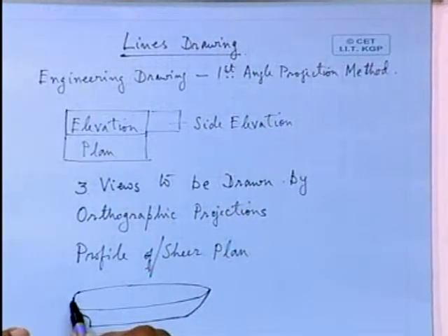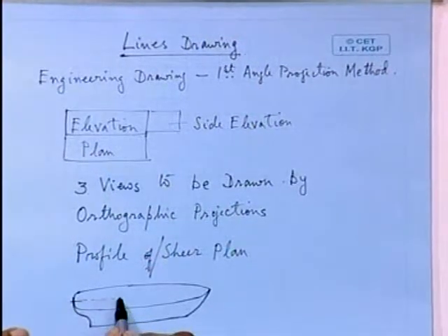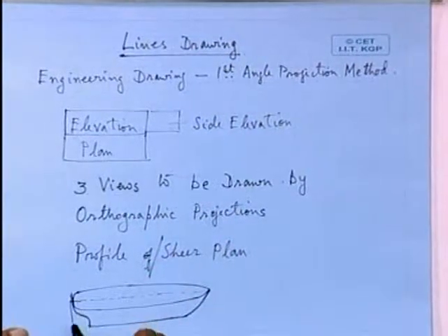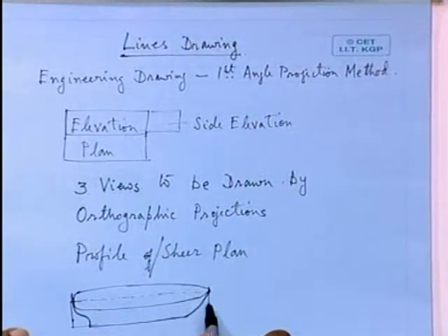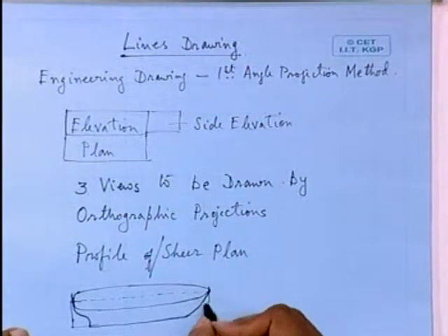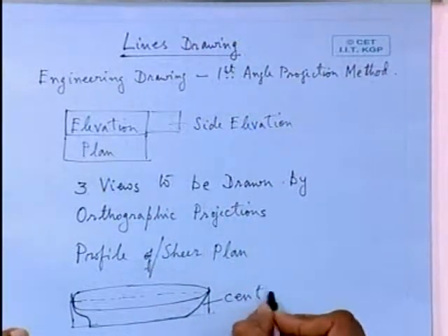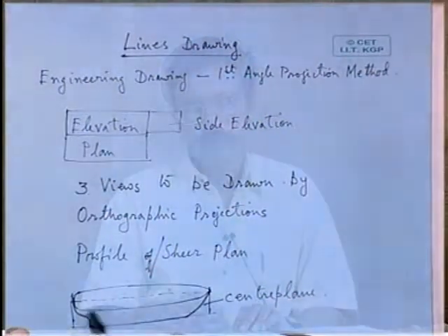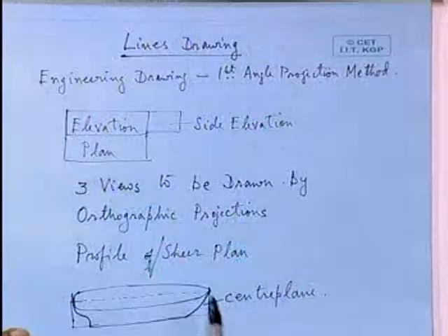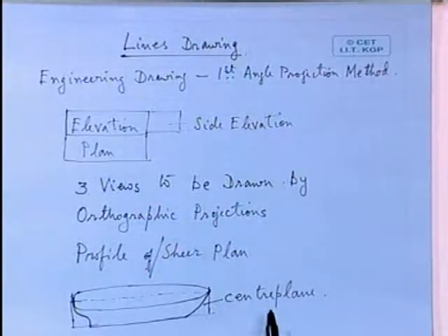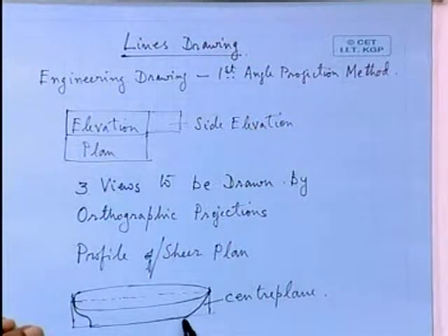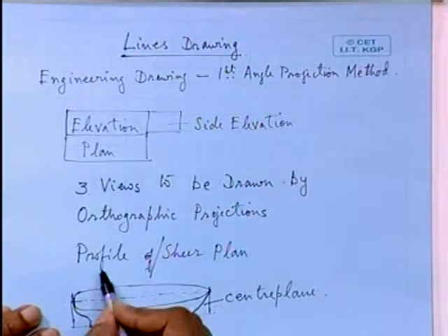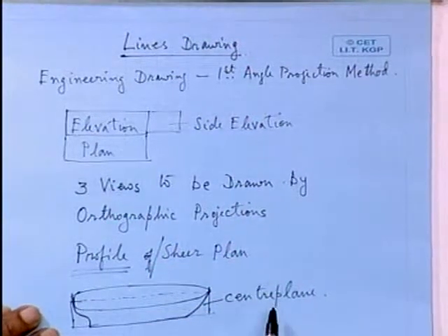Now you make or delineate what is called a center plane. This is your center plane. Now where this center plane intersects the hull, the outline of the boundaries of the hull found by cutting the center plane will give you what is called the profile of the ship.